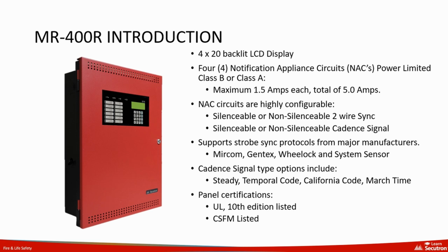NAC circuits on the MR-400R are highly configurable, offering both silenceable and non-silenceable options for 2-wire sync and cadence signals. This flexibility allows the panel to support strobe synchronization protocols from major brands such as Mercom, Gentex, Wheelock, and System Sensor. The MR-400R holds certifications including UL 864 10th edition and CSFM listings.